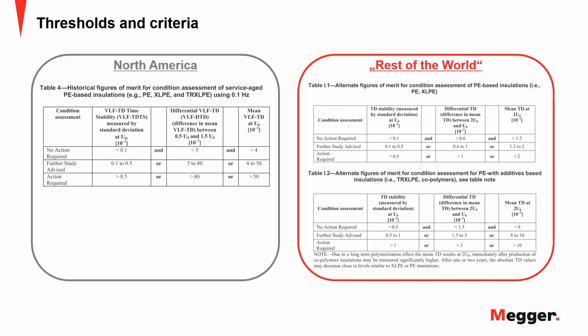If I could just make a comment on this topic too. One of the things that's easy to do with partial discharge values, when you're testing a set of new construction where all your splices and terminations were built at the same time in the same construction project, is this: I would expect to see the same value within reason across all of them.